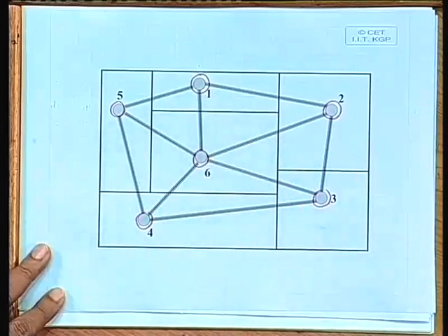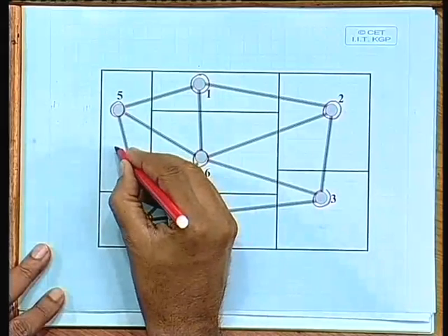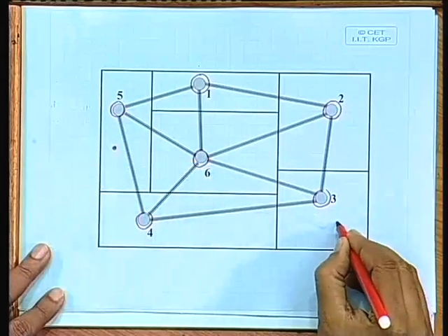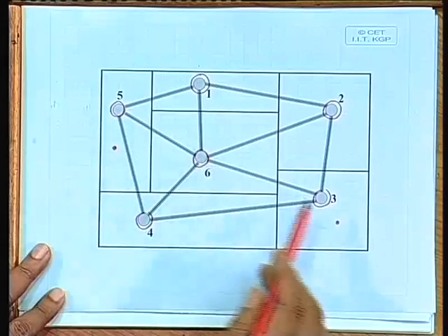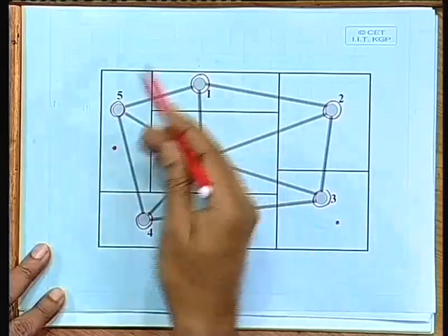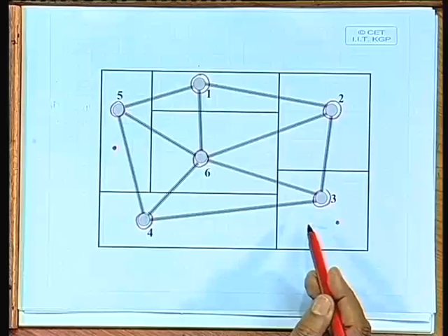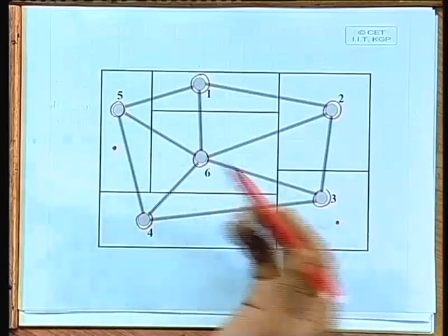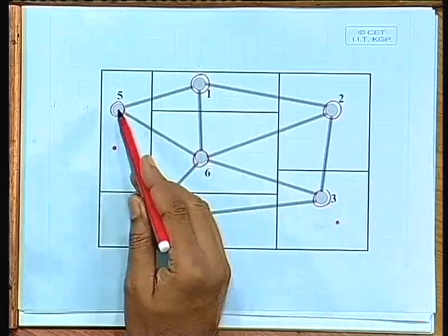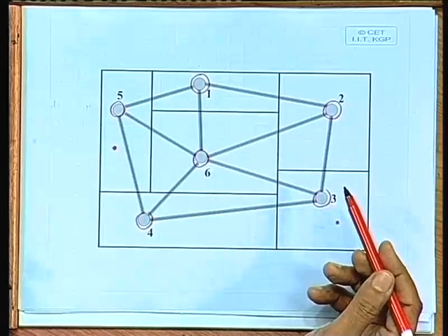So, this is your graph. So, if you want to connect a pin say from here to a pin from here, this boils down to connecting node 5 with node 3. So, in this graph you try to find out a path satisfying the capacity constraint, and if you are also worried about the cost, also satisfying the minimum cost path.